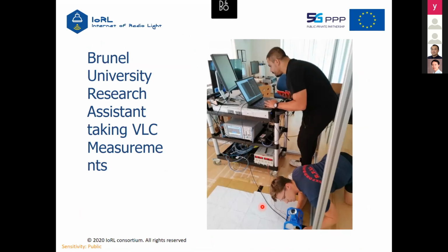So all this system will be fully calibrated. We first do the calibration for the power and also the connection and also the power measurements and also for the distance. So this is for the whole initial setup, and also the signal level at individual stages. And for the base station, we calibrate the base station towards the millimeter wave and also towards the VOC. They have different power levels and also work for different bandwidths.